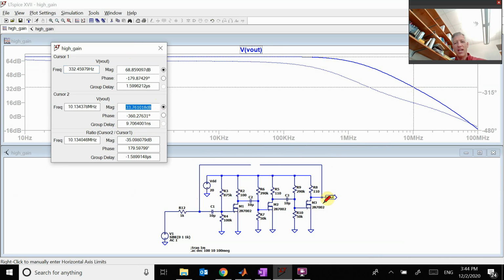So when I change from an inverting to a non-inverting terminal on this op amp, I need to make sure that the gain on each pass or each cycle is less than 1, or less than 0 dB, so that it gets smaller and smaller and smaller rather than bigger and bigger, so that it won't oscillate. And so those terms are called gain and phase margin.